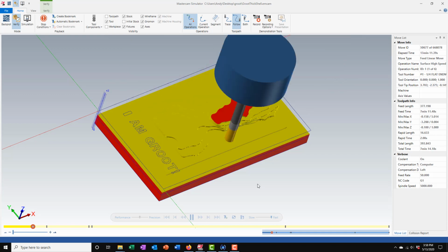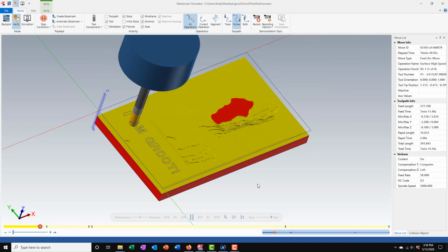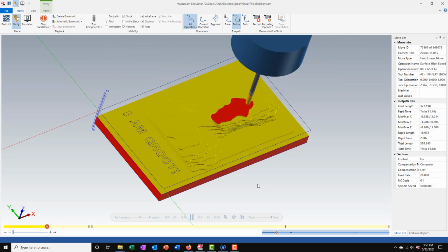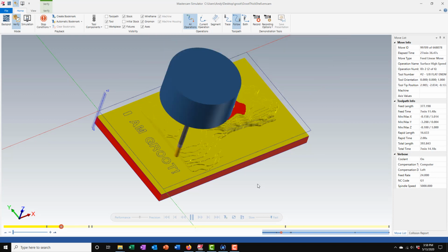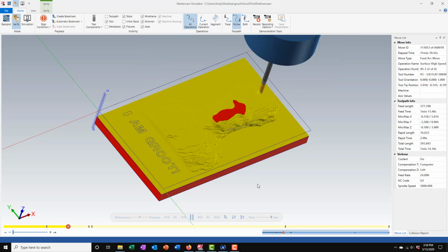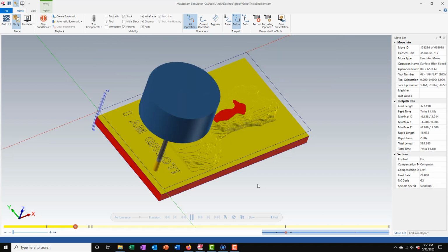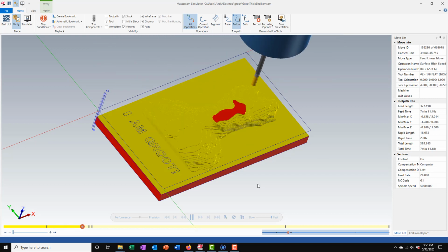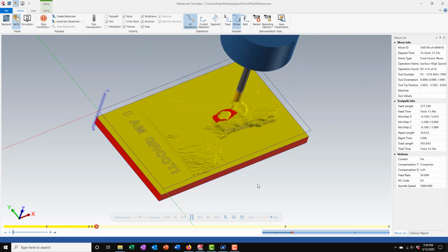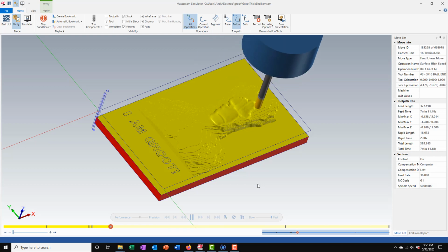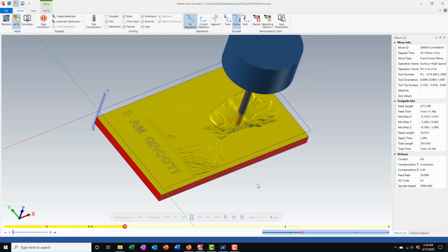And there's our first roughing tool, which we looked at earlier. Now here's the next tool, which is doing the 1/8 inch flat. That's doing the re-rough, which is getting it ready so we can run that 3/16 ball and not run into anything. Now here's the 3/16 ball doing its hybrid toolpath, and this will be the toolpath that probably takes the longest to run time-wise.